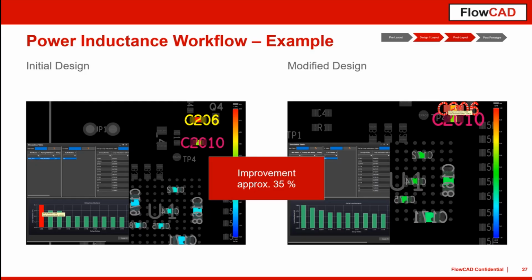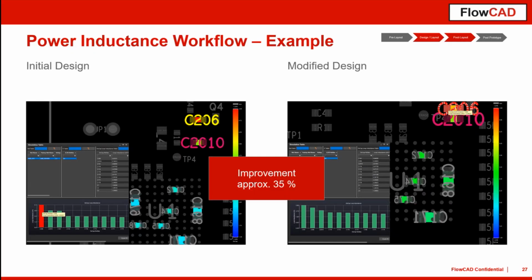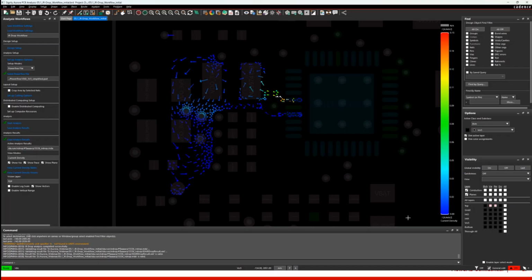As you know, once the decoupling capacitors are too far away from your devices, they do not really work. So you can either delete them, because they do not have any impact on your design, or you can optimize your design by moving those capacitors closer to your IC pins. So the design server itself, how the setup works, I want to show you right now again.